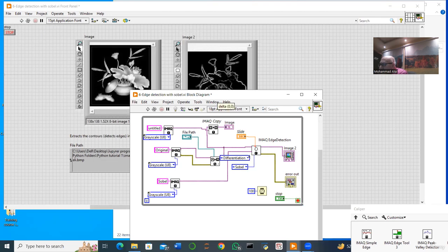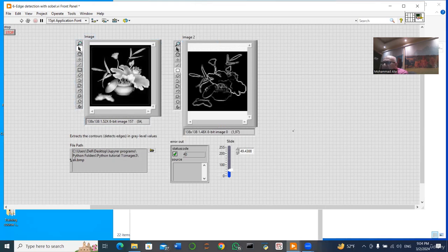Now it is already selected to Sobel, of course, but I can open it, and you can select any of these different models, which give also different quality edge detection. And here, as you see, important to note that the image which we read, it is this image and the input, really.